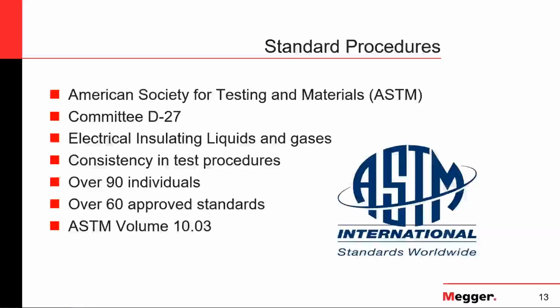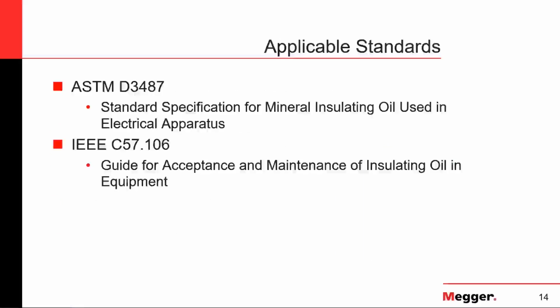Again, focusing on dielectric breakdown voltage, we're going to look mainly into ASTM standards for the actual testing itself, right? The standards published by the American Society for Testing and Materials. And all these standards fall under the D27 committee, the electrical insulating liquids and gases, and are all described in volume 10.03.